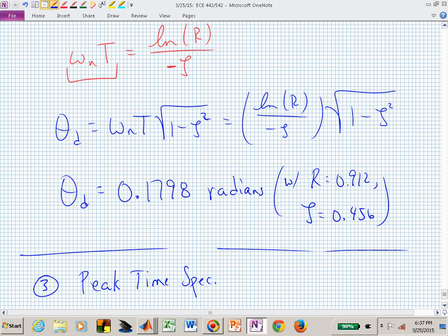Let's just figure out the peak time and then we'll figure that out, okay? We'll think it through. Let's see what the peak time tells us and then see if that's compatible or not. Remember, the peak time, if we have an angle, if we want a quicker peak time, which way does that angle need to be? Bigger or smaller if we want to reduce our peak time?